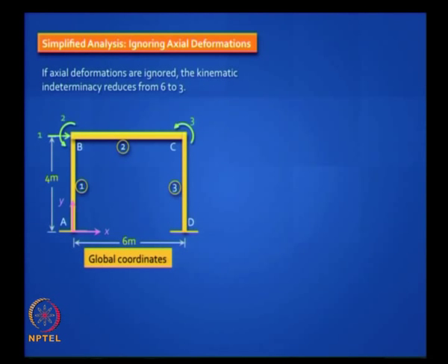This is what we did in slope deflection method and moment distribution method, right. So it is a massive reduction of effort, and let us not waste time in calculating reactions through this technique. So we do not even put global coordinates for reactions. So from a 12 degree of freedom model you are now a 3 degree of freedom model at the structure level.